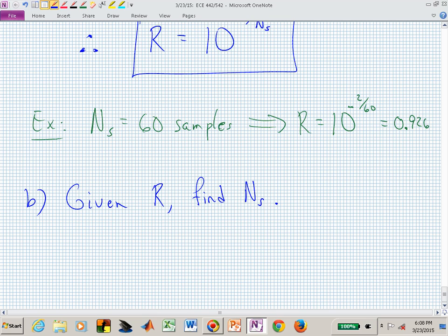Which poles dominate my behavior? The ones that are closest to the unit circle, and usually we want the ones closer to z equal 1, because the others could be banging around a little bit, but it's really the radial distance that impacts the settling time.